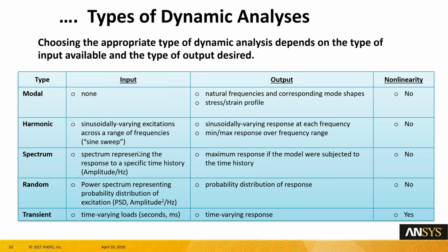So, in summary, for modal analysis as an input, you don't need to have any input. You can take a part, bring it into ANSYS, and without applying any loads or displacement boundary conditions, you can do a modal simulation. What's the output of this? We get the natural frequencies and the mode shapes. And if there's any need, we can also get stress-strain profile.